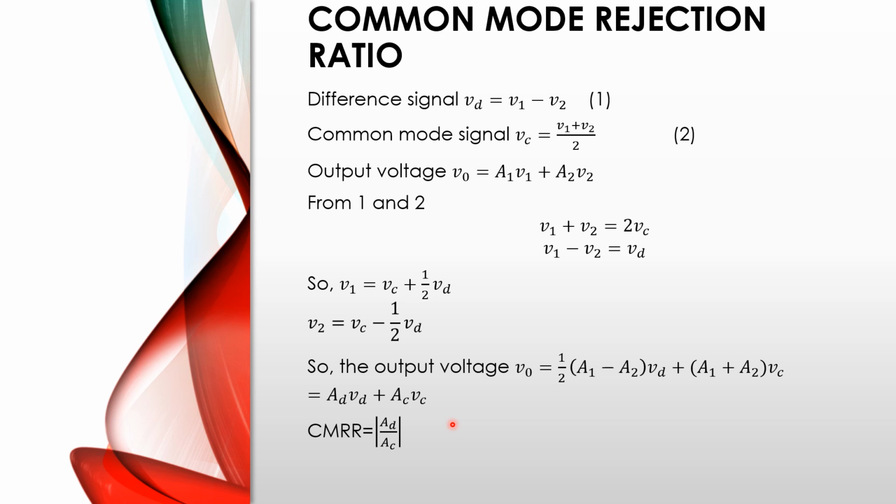Noise means any unwanted input signal. Noise is generally common to both inputs. That means the differential connection tends to provide attenuation of this unwanted input while providing an amplified output of the difference signal applied to the inputs. This operating feature is referred to as common mode rejection.